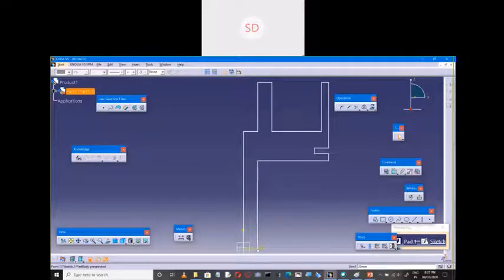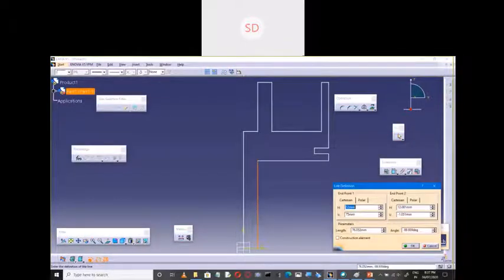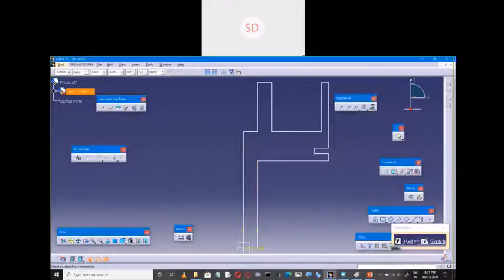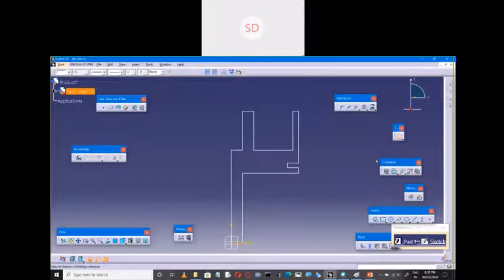You can drag and provide the point here. Otherwise, you just double click this one. So it's going to use its definitions here. So horizontal is 12. Now you make it exactly horizontal as 12. Okay, vertical as 75. Here you make it as 0. Okay, then use a line. You can just join from this point to this point. Now profile is completed. You just exit here.